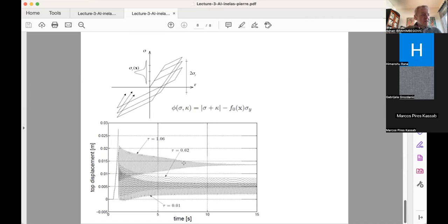And typically you have something called size effect. The size effect means that when you have a small specimen and you establish the ultimate load, it's very likely that in a very large structure the ultimate load will not be the same. And the bad news is that on the very large structure, the ultimate load will be smaller. So we have also worked out these probability estimates for computing the ultimate load on a very large structure which cannot be tested. And these structures which cannot be tested in real size are ample.